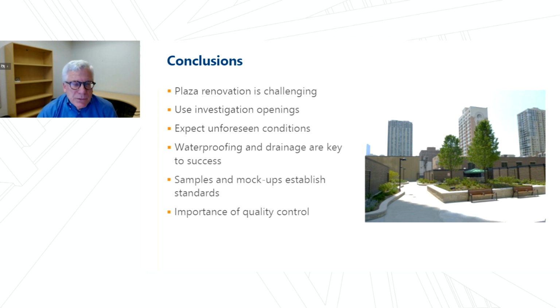Experience in plaza work is really important. You have to use investigation openings to at least get a snapshot of what you're looking at, and you have to make judgments based on that. And what does that mean? You should really expect unforeseen conditions to pop up along the way, and be prepared to modify things on a short basis on how you move forward.